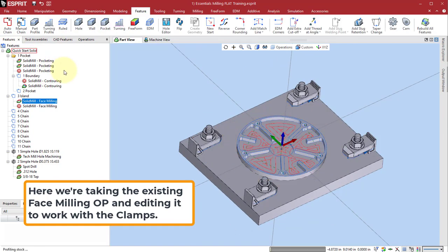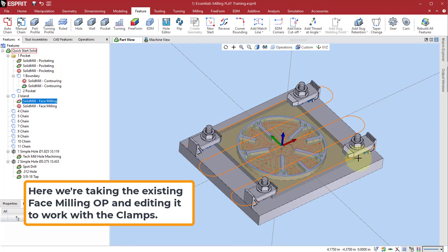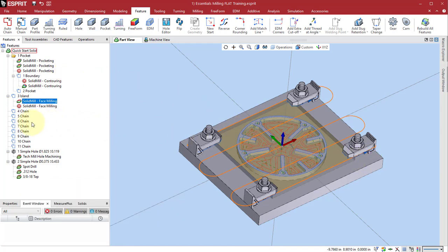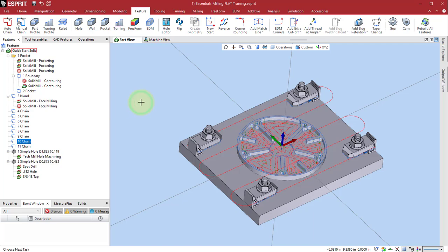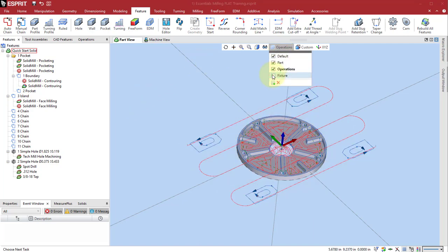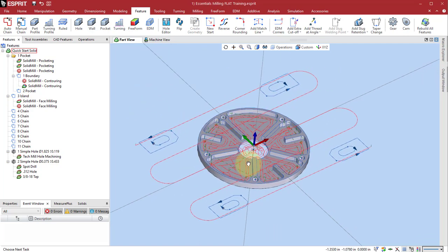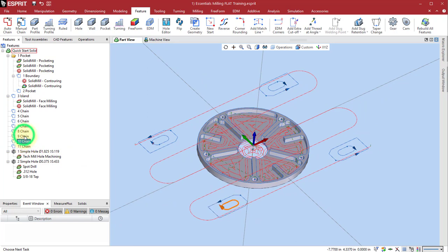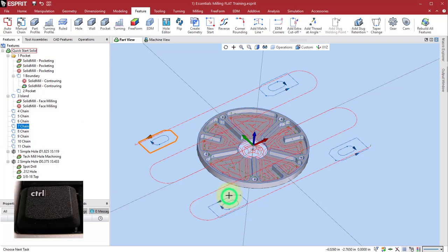See what happens. Toolpath we get now. Now, why did it not avoid those? Well, some of that could well be because of the way that we built those features. Those features themselves, if you'll notice, in fact, let's go to our layers, turn off our fixture. Of course, there's more than one feature, one for the inside, one for the outside. But at any rate, those features also don't have any thickness. That's one of the issues.